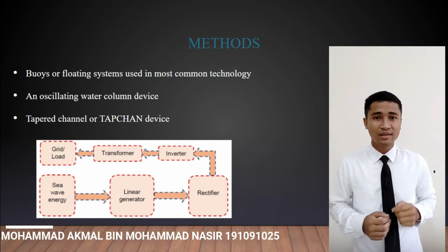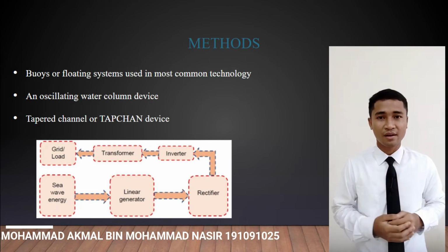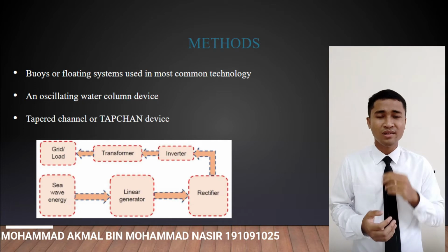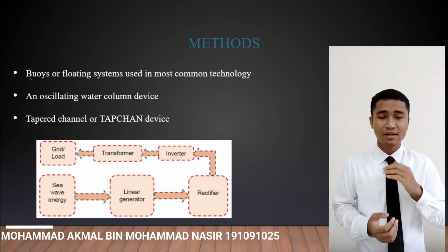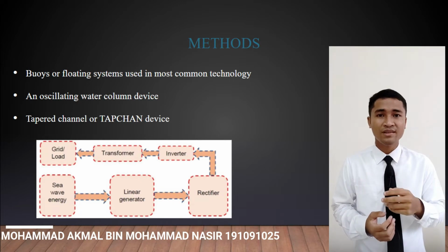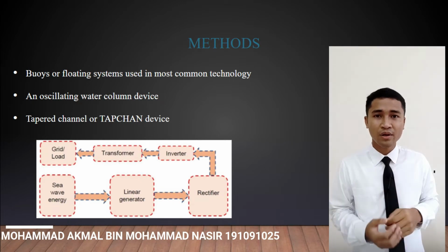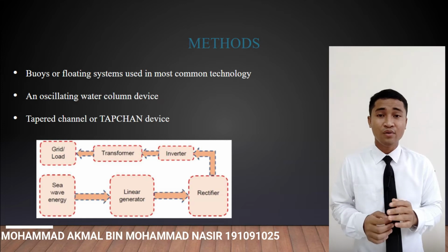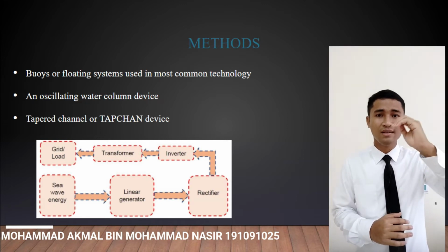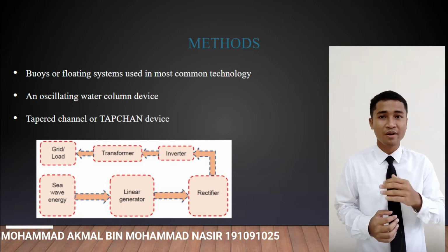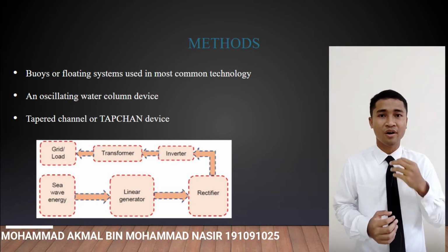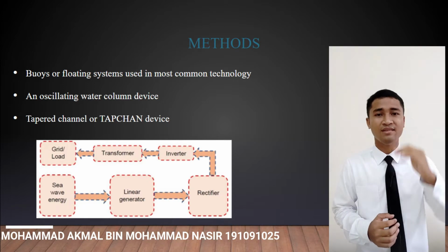The last one is the tapered channel, or TAPCHAN. It is a device which is quite similar to hydroelectric in terms of power conversion, except that it uses waves. When the wave from the sea enters the tapered channel, the wave width decreases. Then the wave amplitude and the pressure will increase according to the conservation of energy, allowing the wave to travel up a ramp and enter a large reservoir, which was built a bit higher than the sea level.